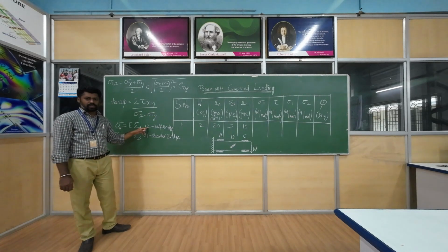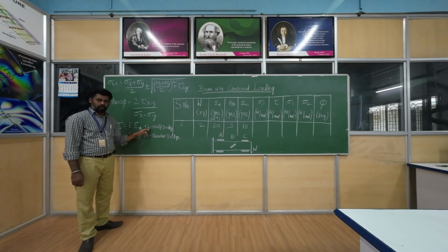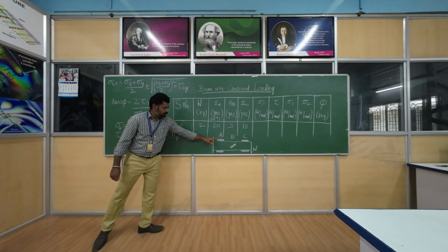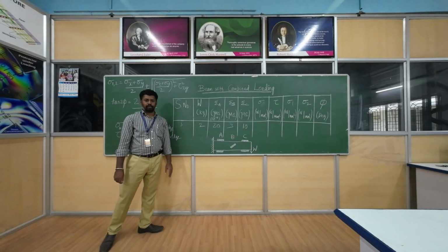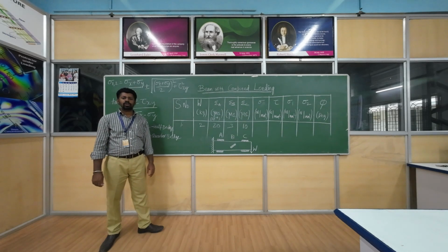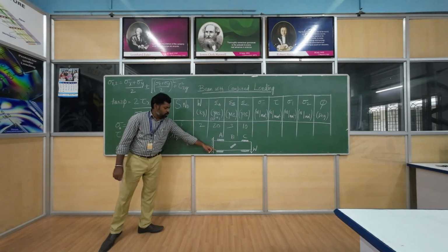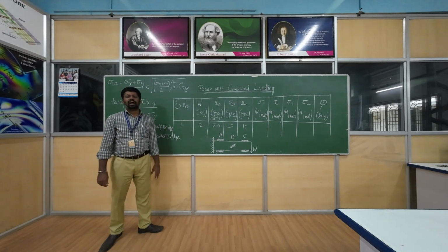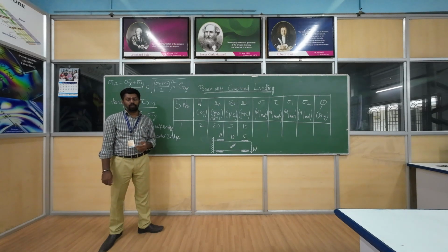If you notice here, I am multiplying by 2. Why am I multiplying by 2? Because we use two strain gauges at section A, which leads to a half bridge circuit. Generally we use a Wheatstone bridge circuit to get the strain data. As we are using two strain gauges, we need a half bridge circuit. If we use four strain gauges, it is called a full bridge circuit.